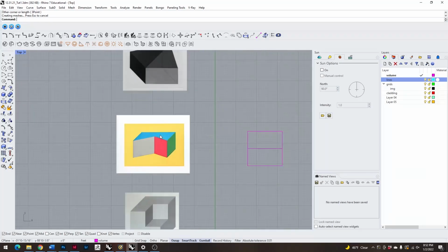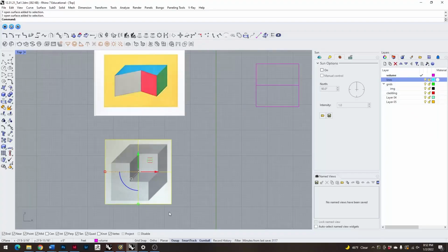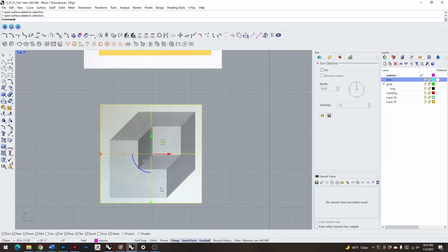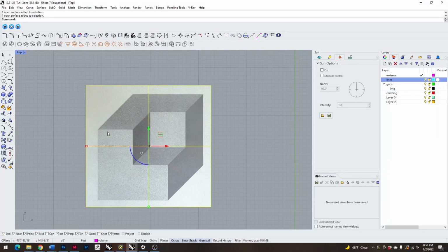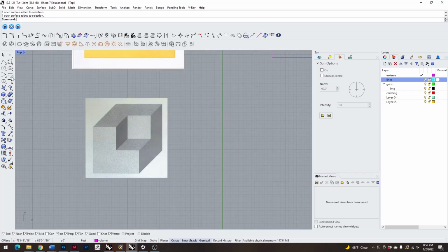Other than that, the basic steps to making these, like this one I guess we can start on. It's pretty easy. It's just a cube, it seems. Using the rectangle command, I just type in rectangle. You can click and make a rectangle or a polyline. Then type in your units, which I'll be using 20 feet, but you may want to use other dimensions.